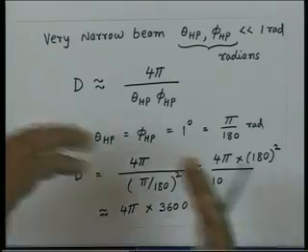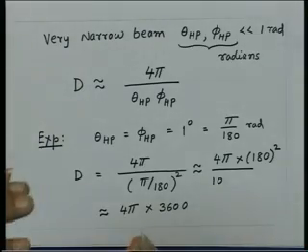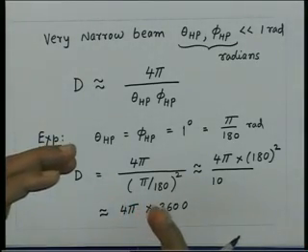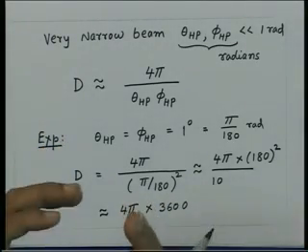So if you take an antenna whose half power beam width is about a degree, then this antenna has a focusing power of about 40,000. What that means is that at a given distance, this antenna would enhance the radiation intensity by a factor of 40,000, and that is very interesting. That is the reason we also call this the gain of the antenna.